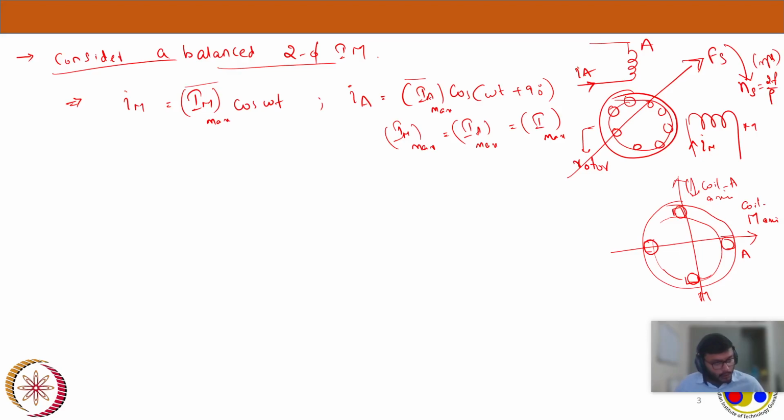Therefore, the torque will be produced, and similarly, we can discuss how the equivalent circuit can be drawn, the same way we did for the three-phase winding. This motor will accelerate in the clockwise direction, and finally my rotor will settle to its speed, Nr. Then we can go for the per phase analysis, which we did for the three-phase machine, and discuss how the air gap power is generated, and eventually derive the torque expression. So all analysis will stay similar.